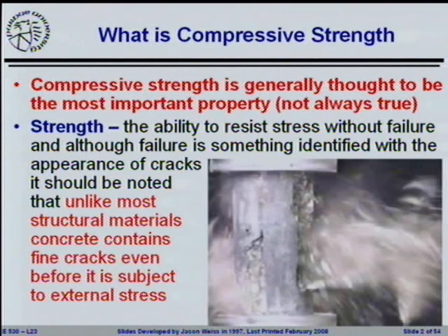And if you get a very, very different compressive strength, you can say, whoa, wait a second, we got something odd going on. Somebody forgot to put in the cement. Somebody added 50 gallons of water too much. There's a big problem out here. Right? But one of the examples of this would be a lot of states measure compressive strength for pavement. Very few pavements fail in compression. Most pavements fail in tension or they fail in something else.